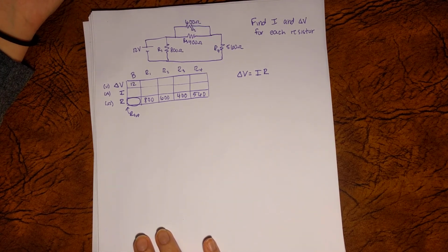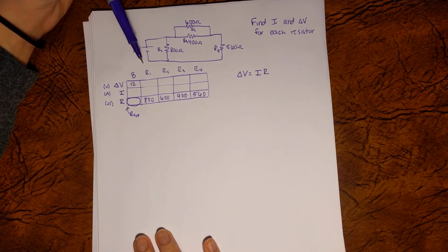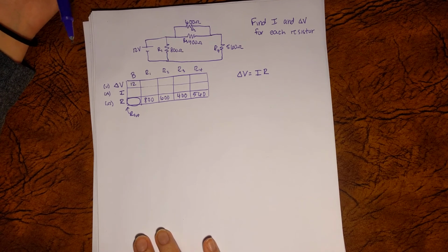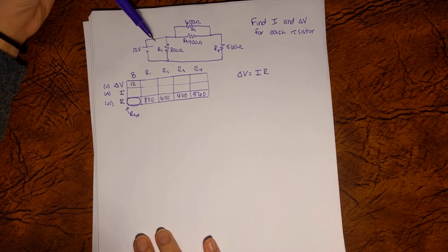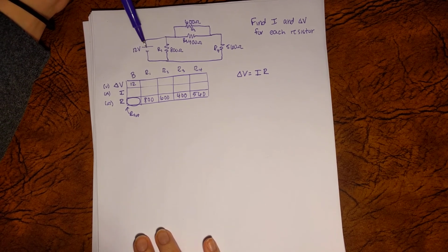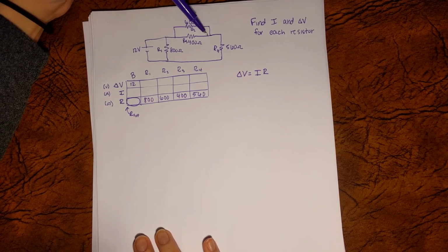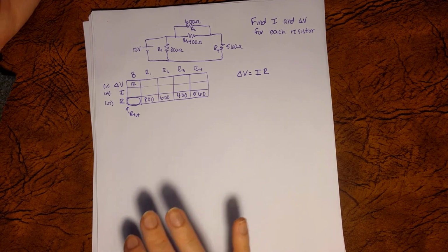And I have also written here Ohm's law. So we know Ohm's law is true, at least assuming we're dealing with ohmic resistors. And the other thing I'll use are Kirchhoff's laws, both his loop law and his junction law. Loop law says that around any loop, the change in voltage should be 0 since energy is conserved. And the junction law says that at any node, so these here are examples of some nodes, the total current going into that node is equal to total current going out of that node. And that's because of conservation of charge.